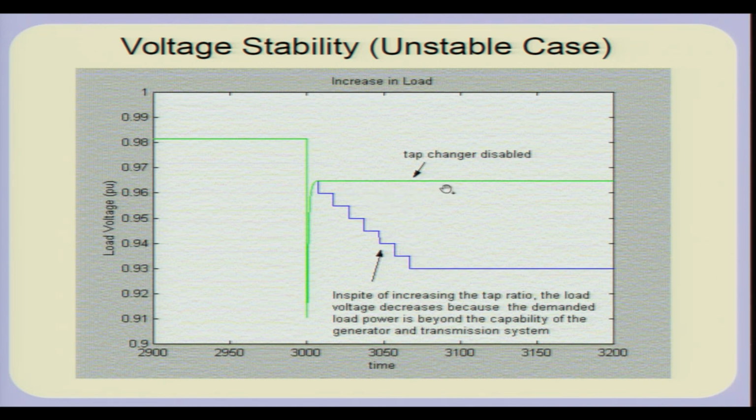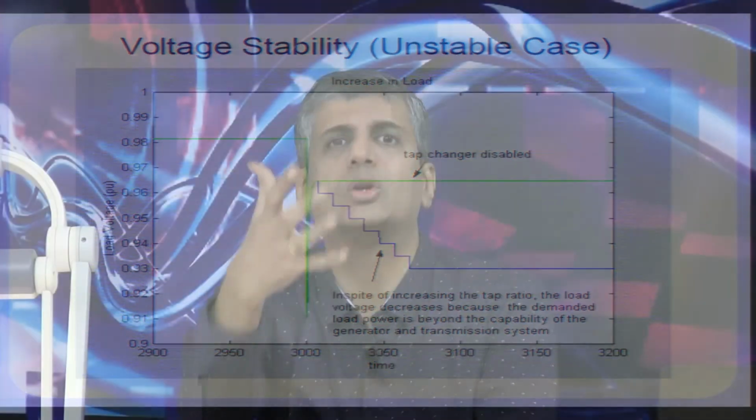So, voltage instability is a dynamical phenomenon where the load tries to act in a way contrary and has unintended effects, because the source impedance at the load becomes very large. In fact, you may cross the so-called voltage stability knee point, and this can happen.